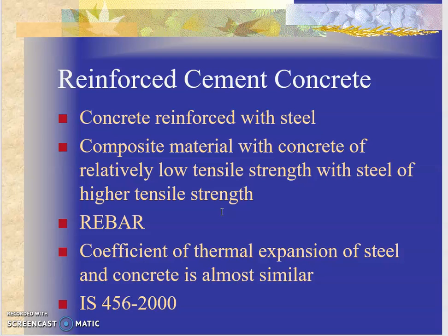And when you have a composite material, there are multiple drawbacks, multiple problems that can arise. First and foremost, any material has a thermal coefficient of shrinking and expansion, okay, that governs the shrinking and expansion at different temperatures. So when you are going to mix two materials, what is most important is that the thermal coefficients have to be similar. If not, you must have seen fine hairline cracks where a beam ends, a beam which is placed over the wall. At the interface of beam and wall, you will always see cracks. Why so? The reason is your beam is made of concrete, RCC. It has a different thermal expansion coefficient. And your walls will be made out of bricks or laterite.